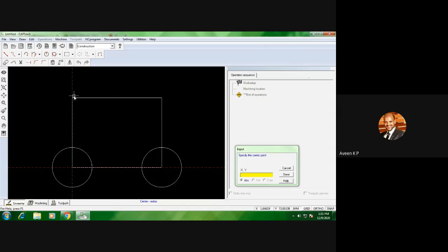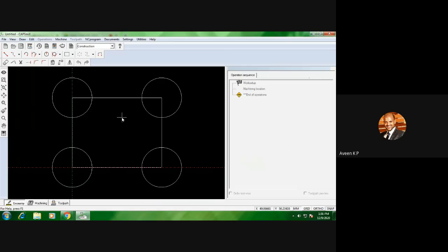You can see that the corner point will highlight. One method is you can type the XY coordinates and locate, or use your cursor, click on the corner point and drag towards right or left, so that you can specify the radius of 20. And the final one at this position, circle of 20, click enter.